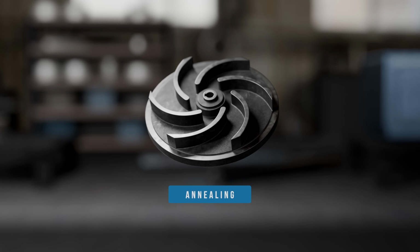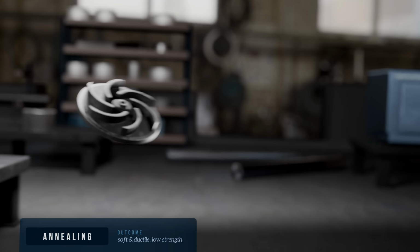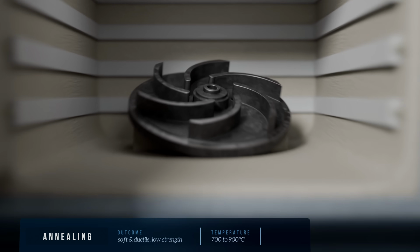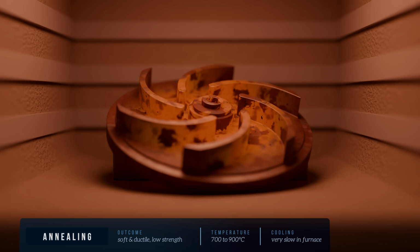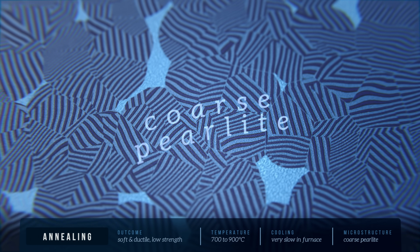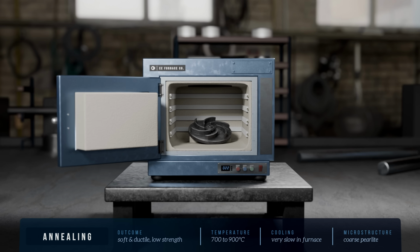Annealing is used to make steel soft, ductile, and easy to work with. It's often applied to steel parts after forging or casting to relieve stresses and make the part easy to machine. The process involves heating the steel into the austenite region, then cooling it very slowly inside the furnace. Because the cooling is so gradual, the carbon atoms have plenty of time to rearrange into the wide ferrite and cementite layers of coarse pearlite, which has low strength, but is very soft and ductile. Annealing is usually a preparation step before machining or other processing.